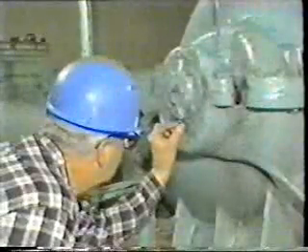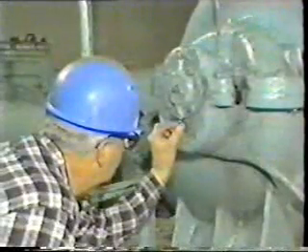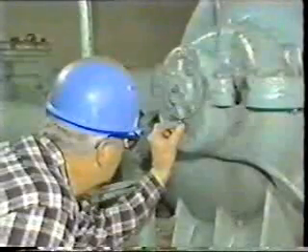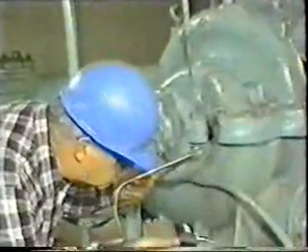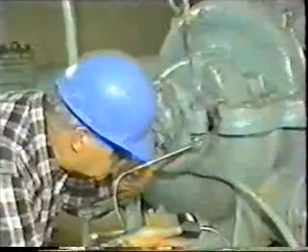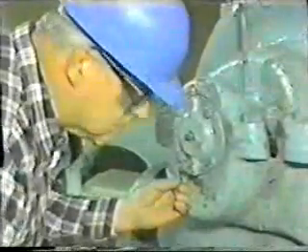If excess grease does ooze out, then you could replace the plug after all the excess grease has drained out. You would have to let the pump run for a while. It could take a while before the temperature would decrease, so you would have to monitor the temperature until it returned to normal. You should also check the condition of the grease to see if contamination is the cause of the overheating.